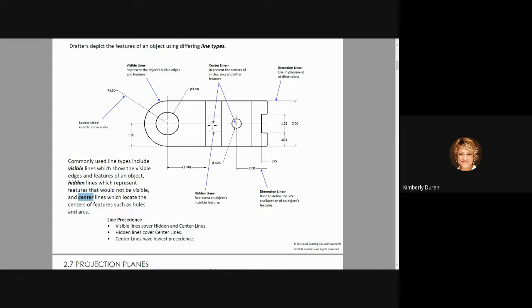It has a straight line and a dash and a straight line. And that's looking at the axis of a cylinder. Could be a cylindrical hole or a cylindrical protrusion. I'll tell you the secret to that. When you have a bullseye in another view, I cannot put a size notation on this where I can't touch it. These dashed lines mean it's hidden. I can't touch that there. We're just showing in this view that there is a void or some feature there.